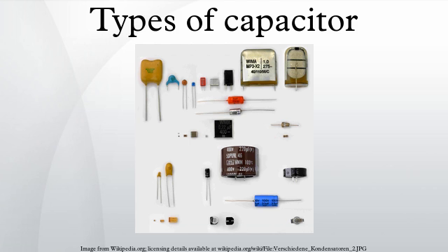For electrolytic capacitors with non-solid electrolyte, mechanical motion of the ions occurs. Their movability is limited so that at higher frequencies not all areas of the roughened anode structure are covered with charge-carrying ions. The higher the anode structure is roughened, the more the capacitance value decreases with increasing frequency. Low-voltage types with highly roughened anodes display capacitance at 100 kHz of approximately 10 to 20% of the value measured at 100 Hz.